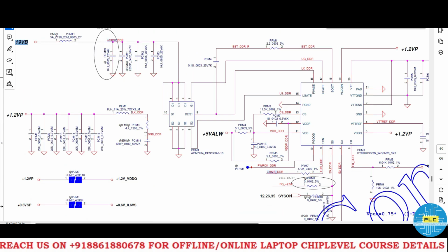See, all capacitors are there. This one is converted as DDR, means it's a RAM section. Here is the high low MOSFET. See, once V in voltage will come here, what you are seeing here, it's a high low MOSFET. All high low MOSFET will be active. Okay, but it won't start working, because the standby voltage will be there till the source, drain. Once the command comes in the phase, then only it will start the low gate and high gate when it activates. Okay, at present it will be 0.